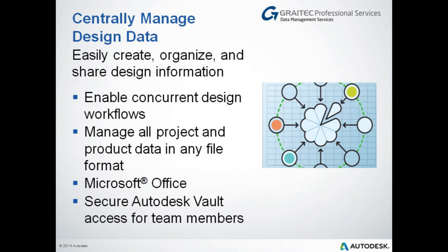And the Vault client resides on the CAD user's machine alongside the add-in within their CAD system, and that talks to the server. When you're working with files, it will pull those files down locally for you, allow you to work on them, and check them out so they're locked to you so nobody else can change them while you're working on them. You save the changes, check them back in, giving relevant comments as to what you've done. That will keep a history, push it back up to the server, and then make your version, the latest version, available for everybody else to work with.